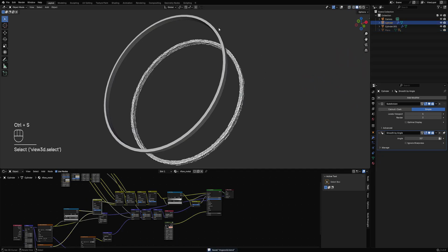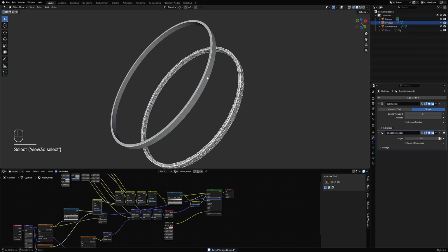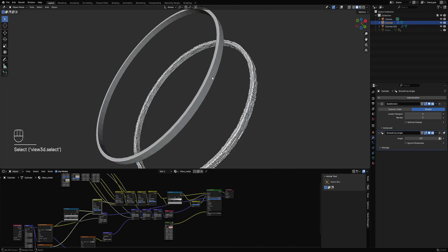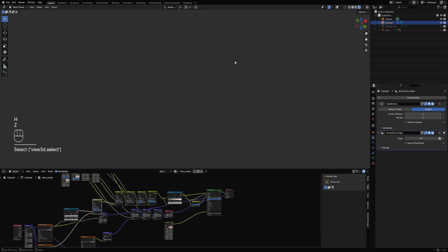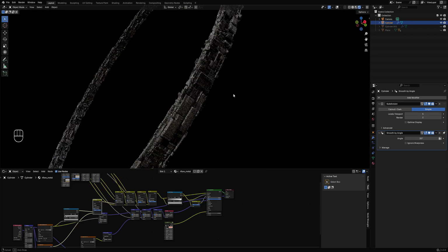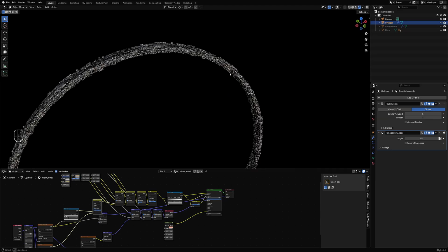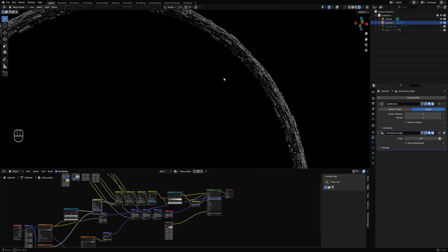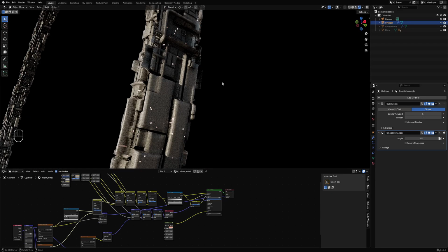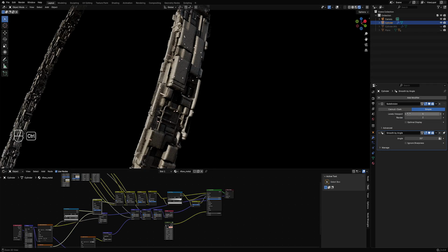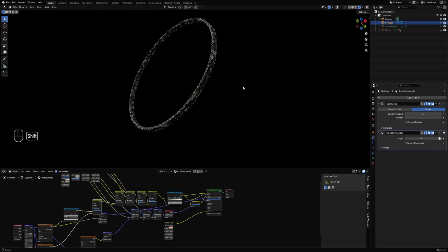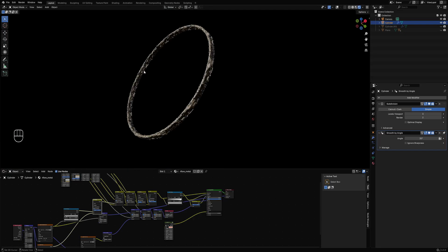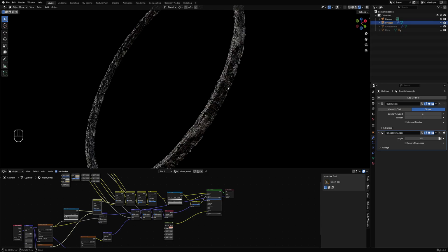Then you can go back and select one of these two, and the one that you need for your scene. So the displacement by shader actually looks really good. And you can see that we used 5 for here instead of 6, and let's use 4. Okay, we can actually get away with 3, and the geometry still looks good.